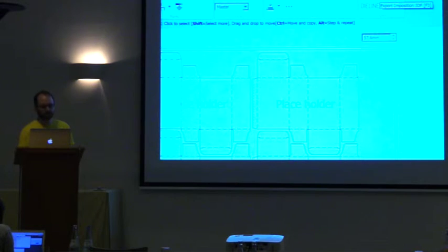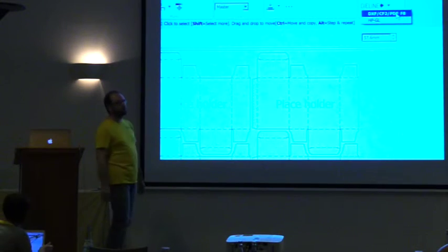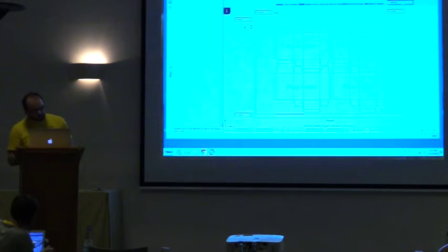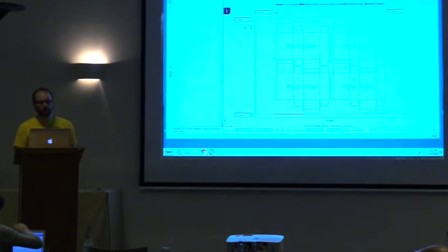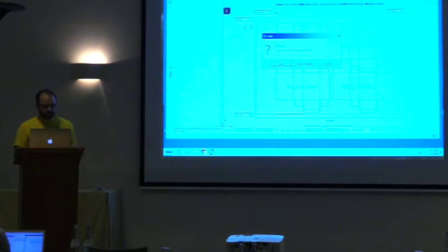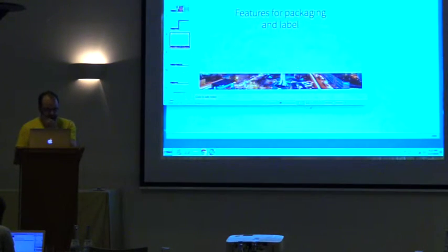So exporting the PDF, exporting JDF for imposition or cutting, or the die line export either in DXF, CF2 or PDF formats or in HTML. Of course, there is a lot more to it, and there are a lot more options that you can specify. But this is the basic workflow that you will go through with IMP when you start to do this kind of imposition.